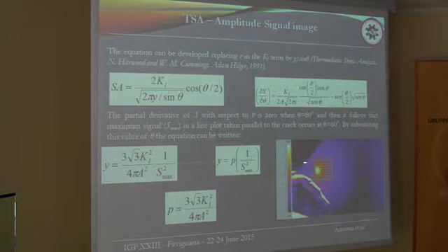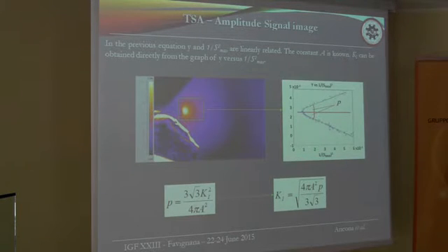a series of plot lines taken parallel to the crack growth direction, we can simplify the equation, considering a linear relation between the y coordinates and the square of the maximum thermoelastic signal, calculated previously by substituting this angle. So it's possible to evaluate the stress intensity factor from this simple equation.